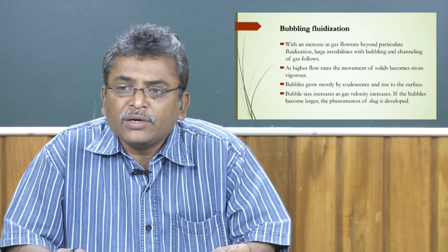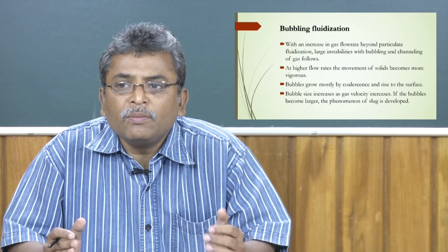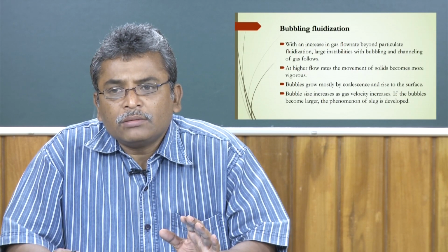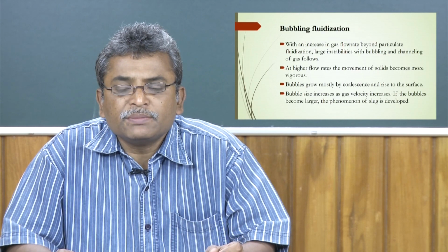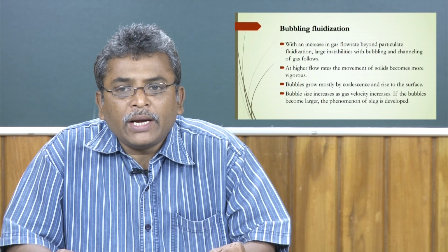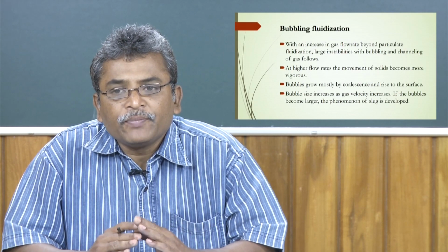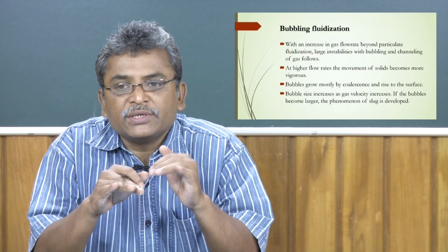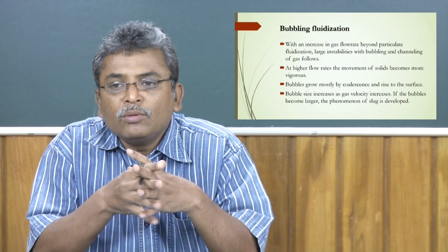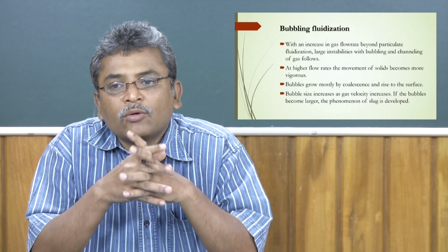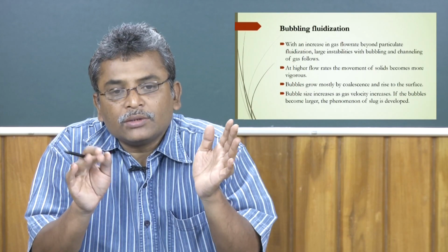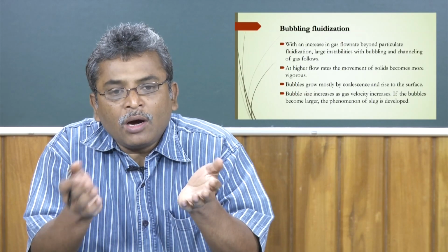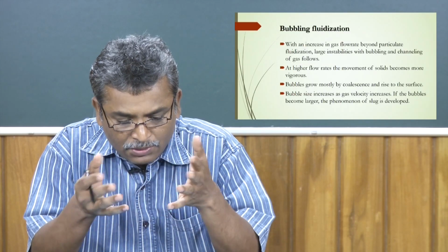In this bubbling fluidization condition, whenever bubbles move up, the bubbles will carry some solid particles from behind by making a wake. Also, from the top, the bubbles will move aside the solid particles, and whenever bubbles reach the surface, they will collapse, and solid particles will be thrown out at the surface. So, this type of phenomenon will happen inside the bubbling fluidized bed.